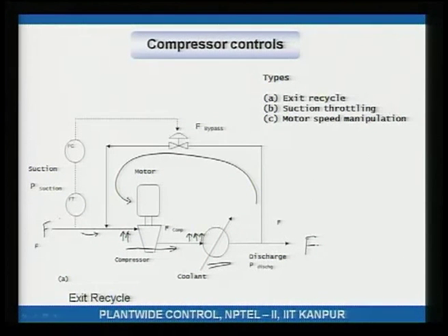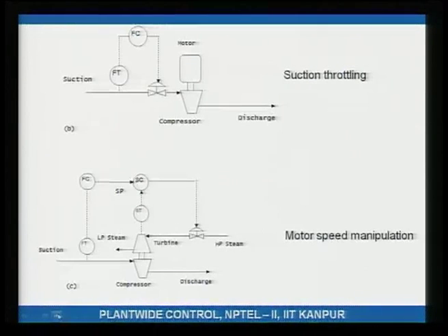If F is decreasing, reduce the bypass, less will get recycled, therefore, F will increase. I hope this is clear. So, by adjusting the recycle rate back to the compressor, you are controlling the fresh feed processed by the compressor by adjusting the recycle rate or the bypass rate.